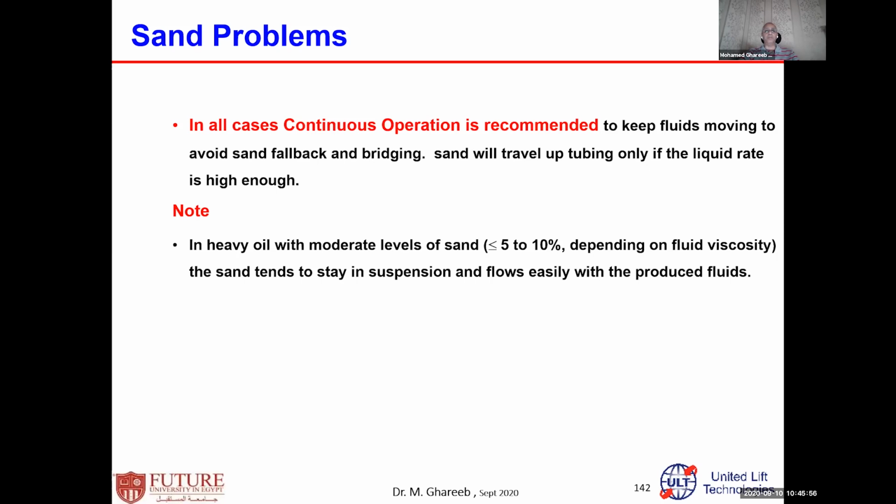In all cases, if you have sand and produce sand, try to keep your pumping running continuously. Try not to stop the pumping. Sometimes people stop the pumping for operational reasons and so on. But in all cases, it's strongly recommended to keep the pump in continuous running operation, to keep the sand moving with the fluid. For heavy crude oil and moderate crude oil, with sand of between 5 to 10%, depending on its viscosity, sand usually tends to be carried, suspended with the fluid, and so on.